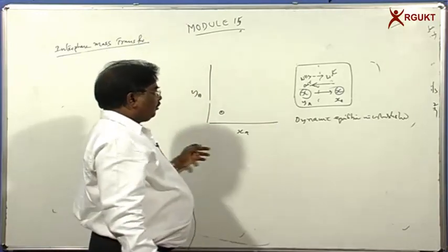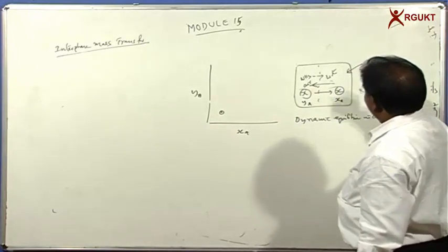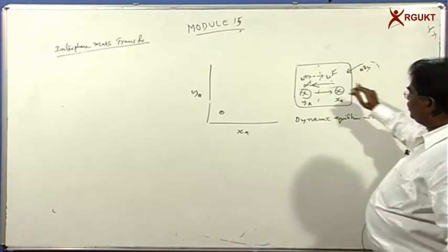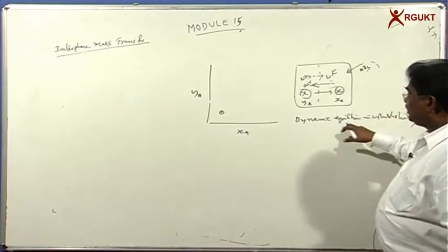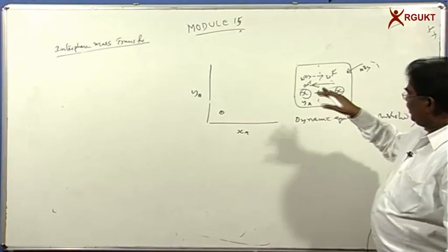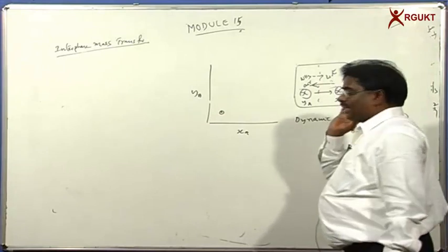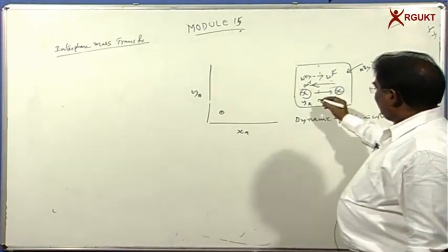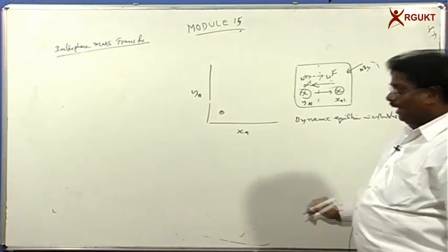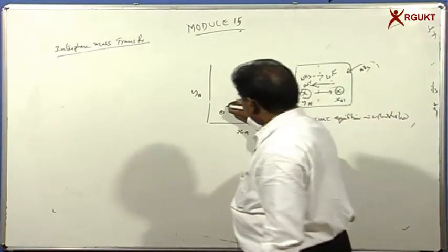Now we can disturb the equilibrium by injecting some amount of ammonia. We can take ammonia in a syringe and inject it into the system. So now what will happen? The equilibrium is disturbed. Again the process takes place from the gas phase to the liquid phase, and from the liquid phase to the gas phase. The process goes on, and ultimately it reaches a new equilibrium. At that time, if we measure the concentration, it is going to become Ya1 and Xa1, but this Ya1 and Xa1 are a little higher than the previous Ya and Xa. So we can represent this as another point.